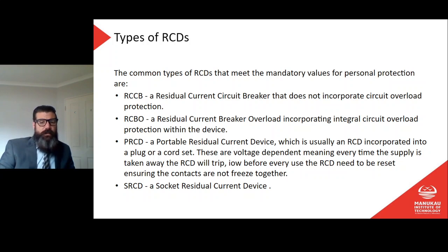But obviously after RCDs existed, people were installing them in wet and damp situations, bathrooms in particular. And then when the requirement that all socket outlets be protected came in, we stopped using these generally, because why would I bother? I just put an RCD in the switchboard, and that covers all of the sockets. I don't need a special one at the socket outlet in the bathroom. But this is a socket outlet that has an RCD incorporated in it, and you'll see that by the green and blue button on there, which tells you that that's an RCD socket outlet.